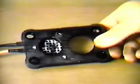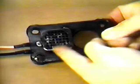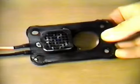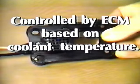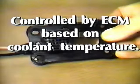The second type, the heated grid, is located right below the primary bore of the carburetor. The grid gets warm with only 12 volts of current and heats up the air-fuel mixture, thereby improving atomization of the fuel. This grid is also controlled by the computer based on coolant temperature.